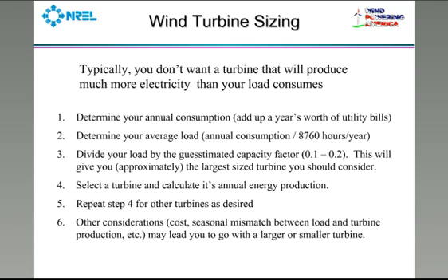Wind turbine sizing. I'll give you an algorithm for determining kind of the biggest turbine you should be considering for a given load. Typically you don't want your turbine to produce more electricity over the course of the year than your load consumes. Typically it's not going to pay off to do that.